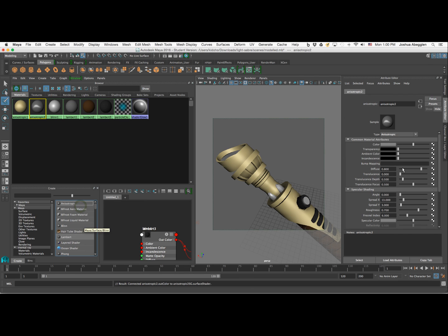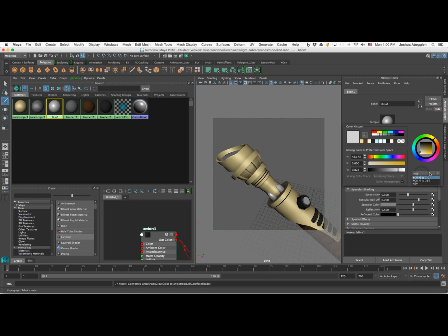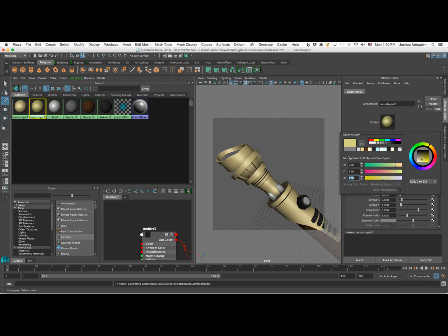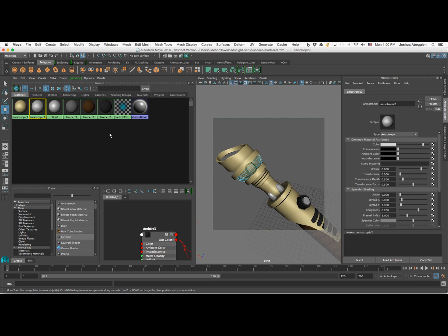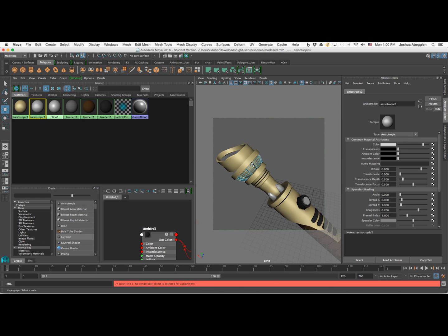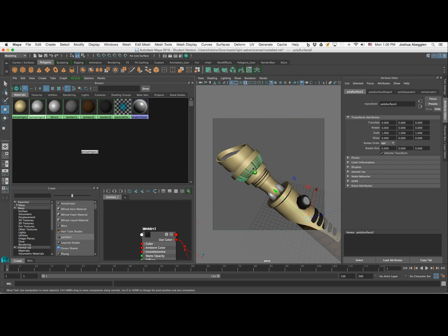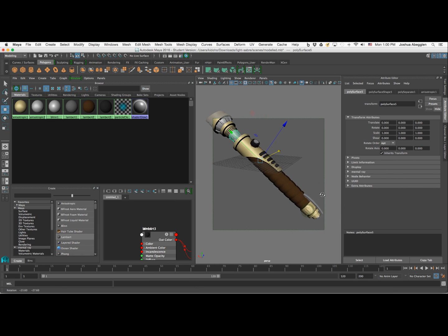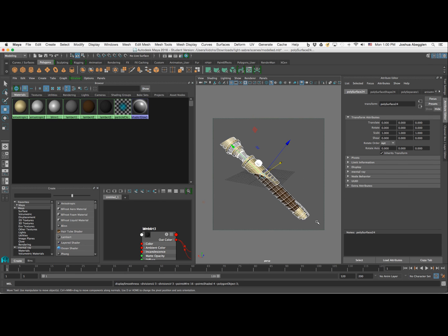Okay, I'm going to create another anisotropic material. I'm going to change my spread to 6 as well for this one. And actually I want to use the same color that I used in this blend, which is, if I click on this little drop down, I can do RGB 0 to 255 and say it's 210 across the R, G, and B channels. I'm going to go ahead and go with that for right now. So I'm going to select everything, go into smooth preview mode, click on view, come back to my render camera bookmarks, and do another render.